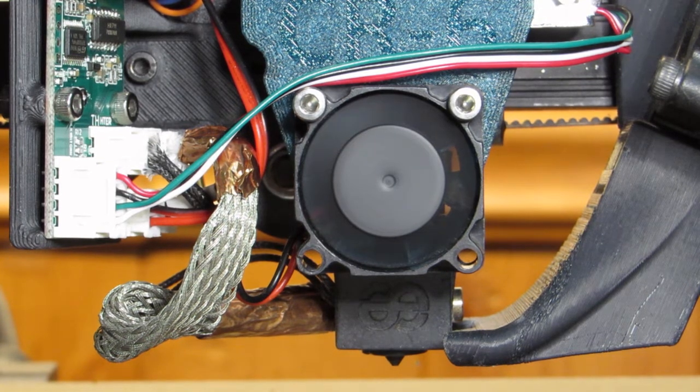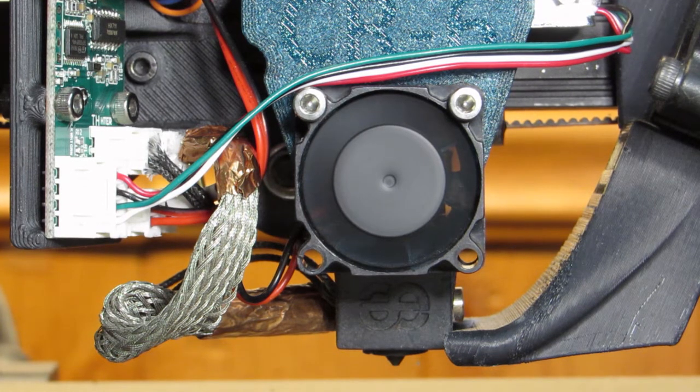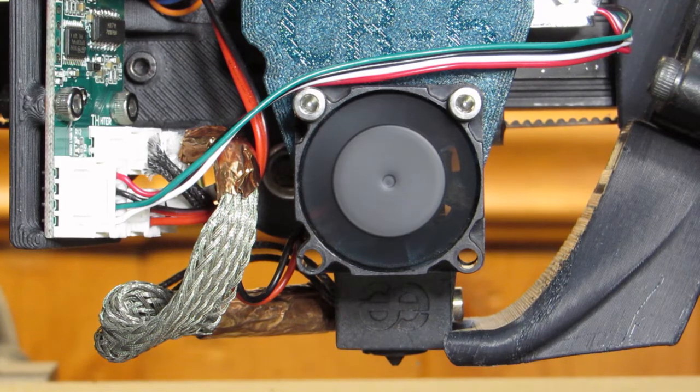With the CR6, there is no difference between the tip of the nozzle and the probe in the X and Y directions, and that's because the nozzle is the probe. That is not always the case on other printers. But when it comes to Z, even though the tip of the nozzle is what's hitting the bed, when it decides, oh, zero's right there, the way it detects that it has hit something is of necessity going to cause it to go past that thing.